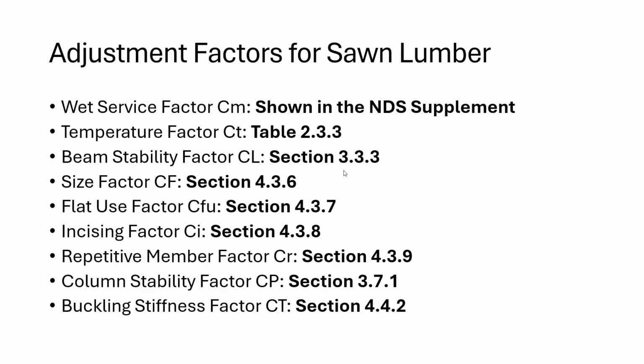And if you don't take that into account, 200 psi is a lot if you start talking about getting close to the utilization ratio of that section. So you really want to be careful that you're taking that into account for a conservative design.